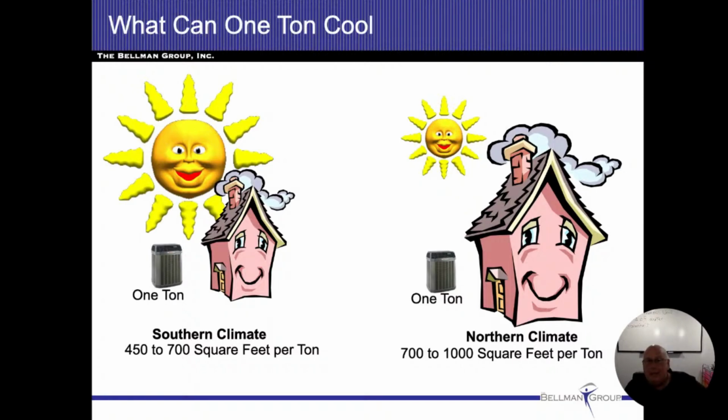So we don't divide everything up when we're doing it and say, well, wait a minute, you've got 5 tons now for a 1,500 square foot home. What I do know is that for the most part, my second floor air conditioning and heating system is going to be running in the summertime more. Heat is going to rise, and I have an open staircase. So that's the one that's going to be doing most of the work. The first floor one would hardly run at all, but if the heat does come in there, it does actually run.